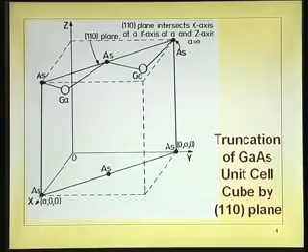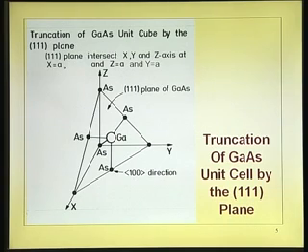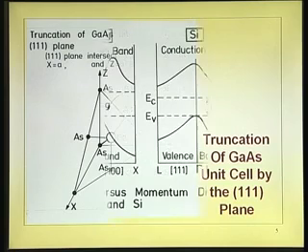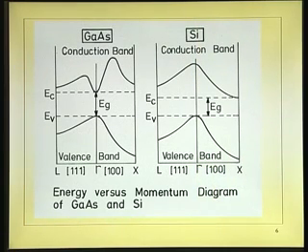Now, I think more or less we have completed the crystal structure and its importance, cleavage plane, etc., and its profound effect on the chip size, chip surface and its usefulness on optoelectronic devices, and also the atoms being 100, 111, etc. also we have discussed. This particular thing also is the other property which we have seen already, that is silicon is indirect band gap, gallium arsenide is direct band gap.